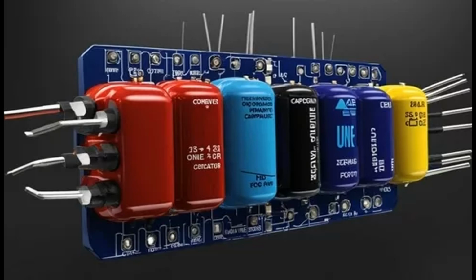Power factor correction. Description: capacitors are used to correct the power factor in AC power systems, improving the efficiency of power conversion and reducing losses. How it works: by adding capacitors to an AC circuit, the phase difference between voltage and current is adjusted, improving the overall power factor. Example: in industrial settings, capacitors are used to correct the power factor of motors and other inductive loads, enhancing the efficiency of the power system.